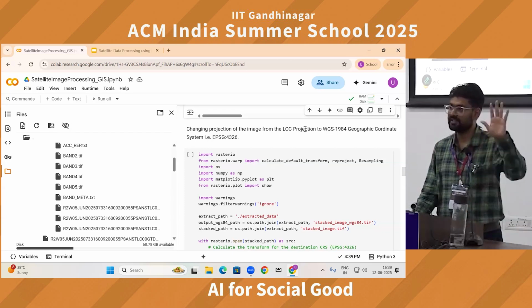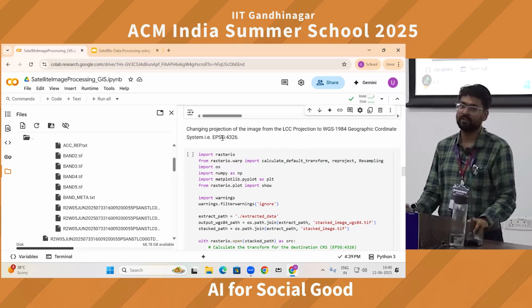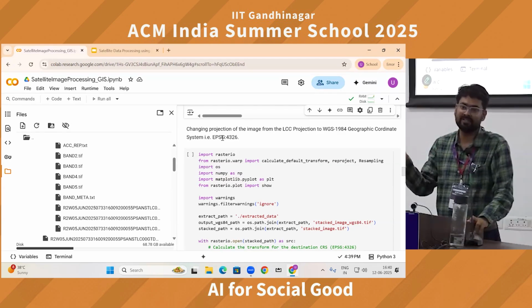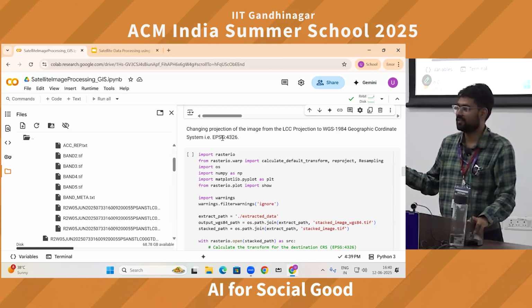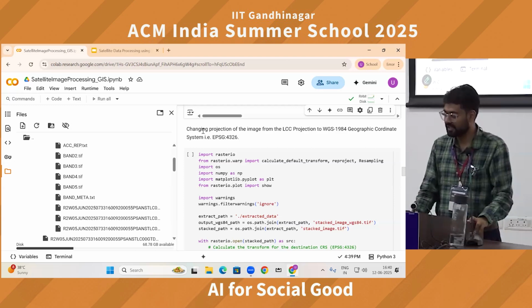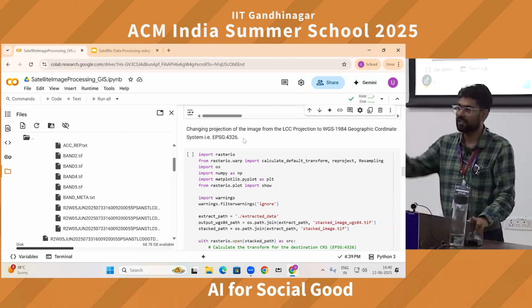So here the LCC projection was the input projection, and WGS 1984 has the code EPSG 4326. EPSG is basically the European Petroleum Survey Group, which gives standard codes to every projection, because otherwise there would be millions of projections. You can also develop your own projection, which can give an accurate CRS for your local area. So there is a need to standardize this, and EPSG did that, giving 3-digit, 4-digit, or 5-digit numbers to various projection systems.